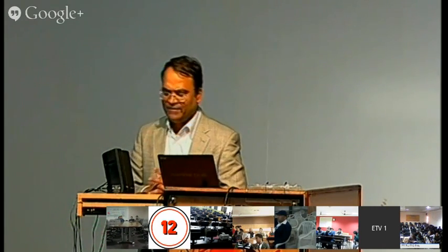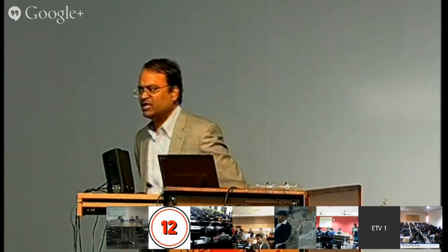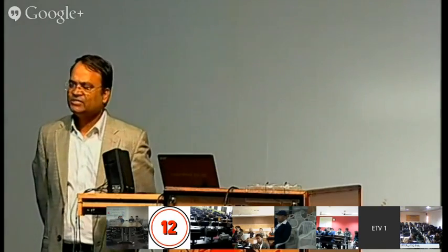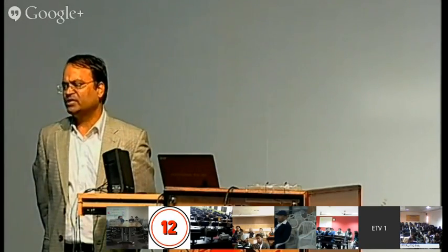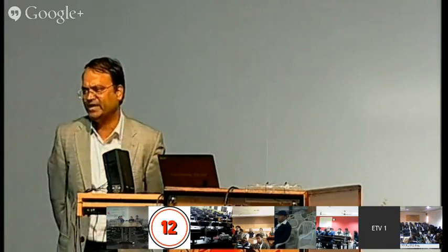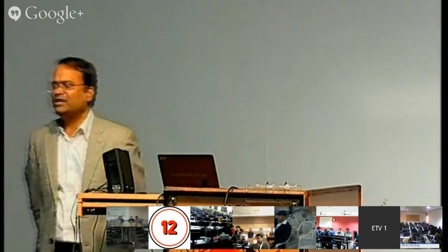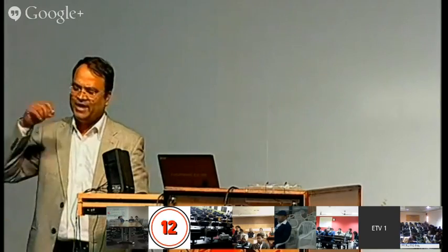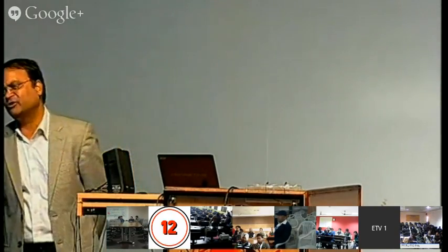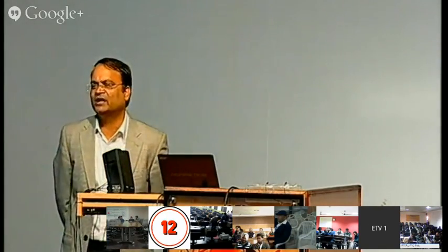See, one portion I said is that we have a motorized rig. On the motorized rig we run tests for 2000, 3000 hours, and we create a very hostile environment, because we keep adding dust, dirt, etc. in the lubricant, and there we have assessed that wear is not taking place and the profile is stable.